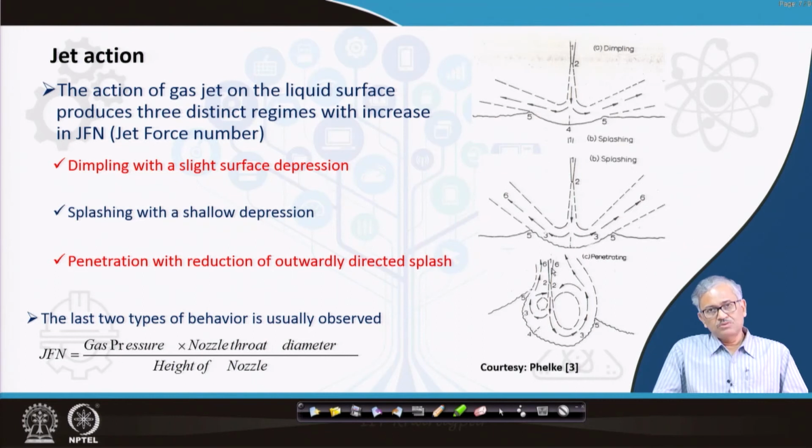And in that case, you can blow a little softer. You can make a quite soft blow. In case of the soft blow, what happens? You decrease the GFN by taking the lance away from the bath. So you can decrease the GFN, and then when the GFN decreases, your rate of formation of FeO becomes more than that of decarburization. That is, you can build up the FeO in the slag, and that is sometimes required. I will talk about that thing. That is the slag practice people do.